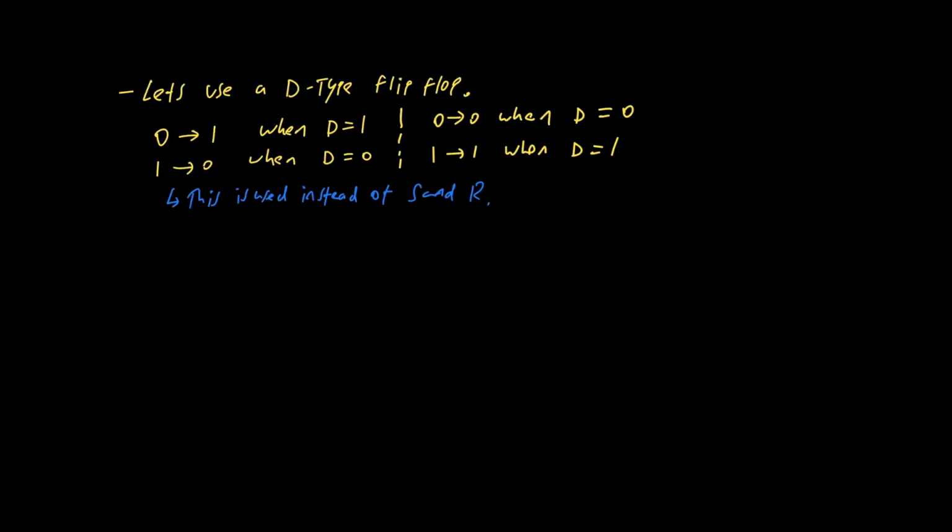In order to design, we need to select the flip-flop technology to use. Here we will use a D-type flip-flop. All this does is require a single input, D, which has logic that covers both S and R inputs, so it is no different in function. It is just simpler to have only a single input. You can see the behavior as written, so when D is 1, it acts as a set condition, and when D is 0, it acts as a reset condition.